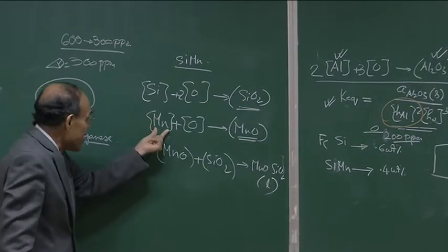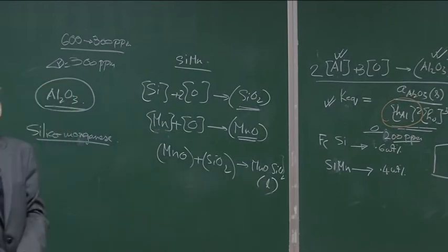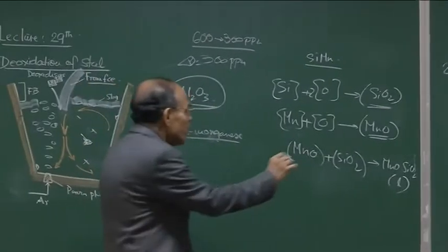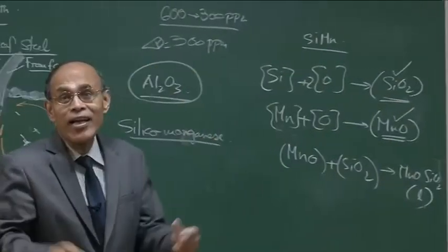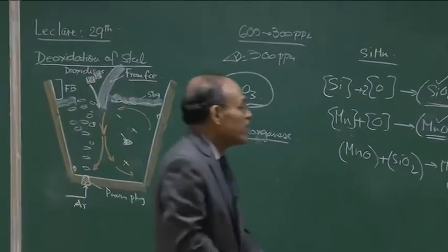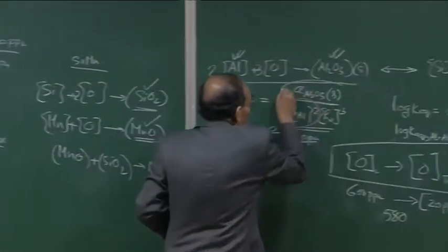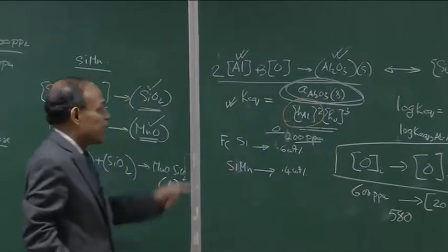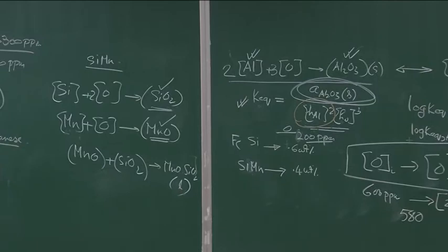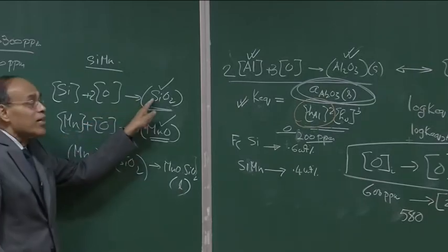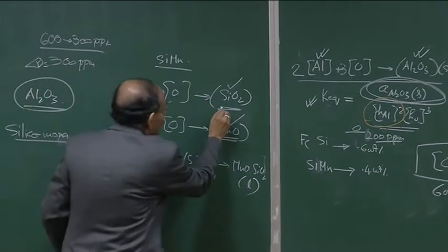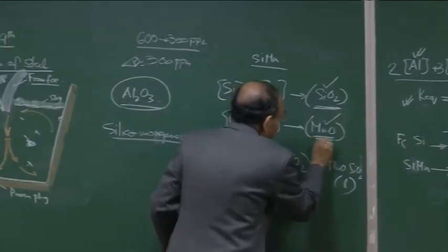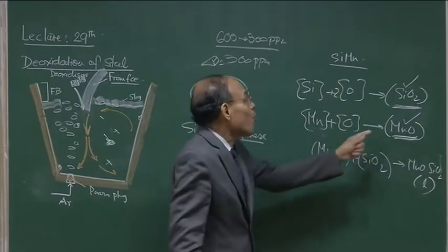But the calculation of hMn and hSi is not going to be straightforward, because silica and MnO are in a combined state. As opposed to the activity of Al2O3, which I have taken to be unity in calculating the total aluminum requirement, I cannot substitute a unit activity.